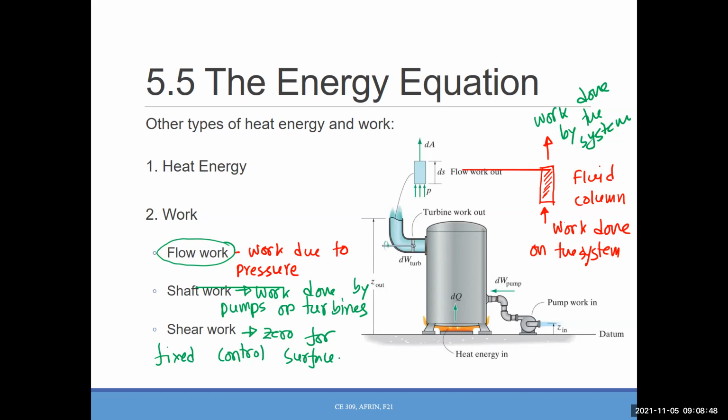So that is basically like some fluid particle is coming in, something is going out, and something is happening within the classroom, or the control volume. In total, that is the total rate of change of something, right? It can be mass, it can be momentum, it can be energy. That was the Reynolds transport theorem.